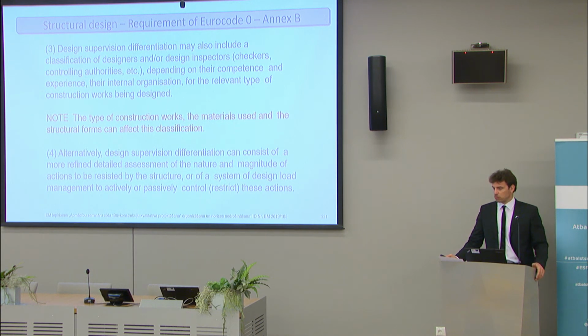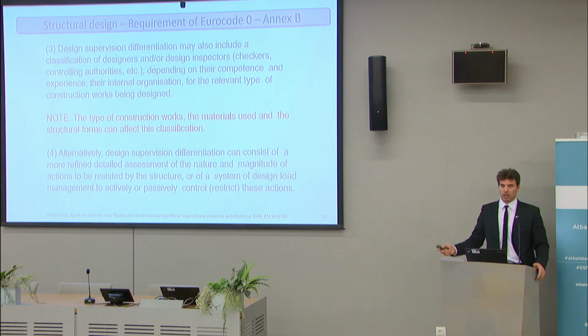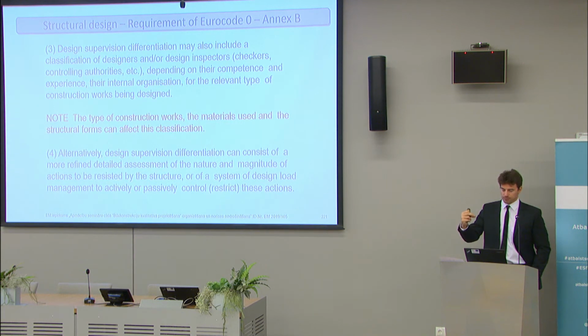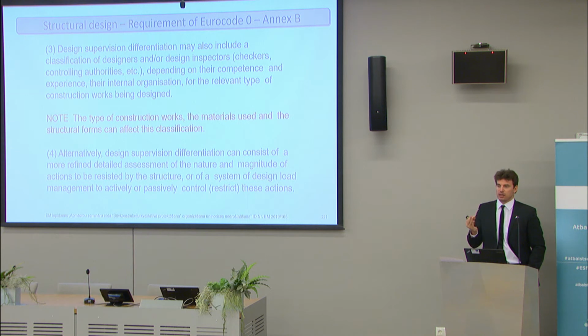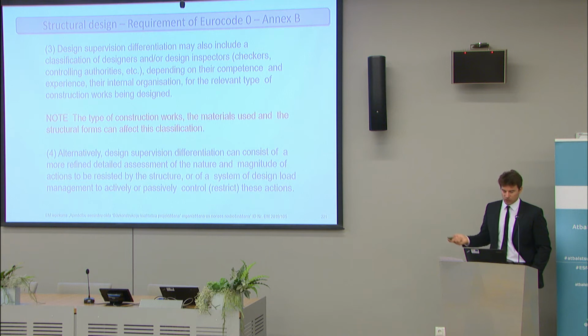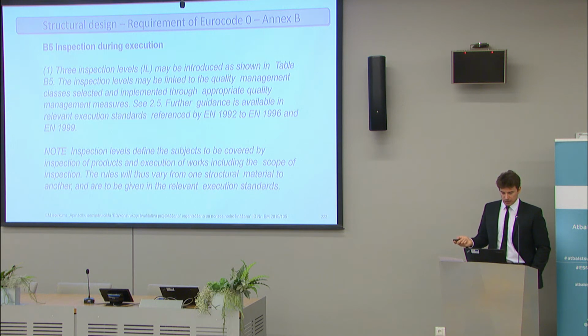Or also, for example, for checking structures, in some cases, at least for checking a calculation afterwards, you can reduce the material partial factors if you have very detailed information about how much the load on your bridge is, for example because you measured it. But this depends very much on the project you are approaching.